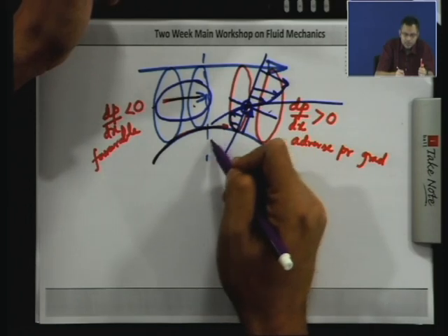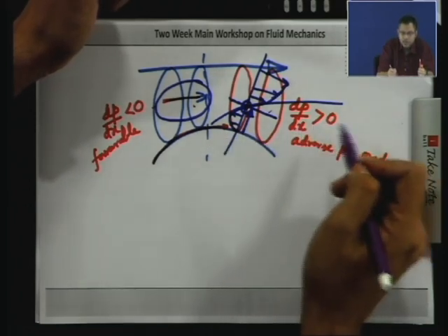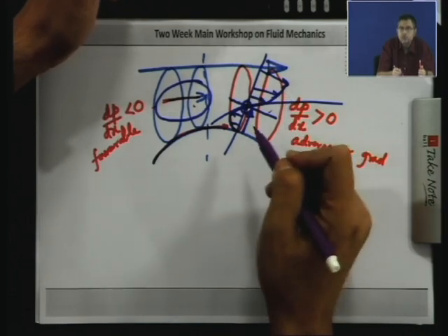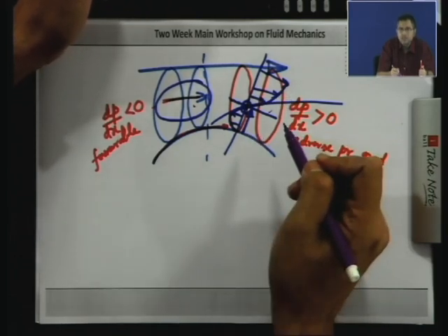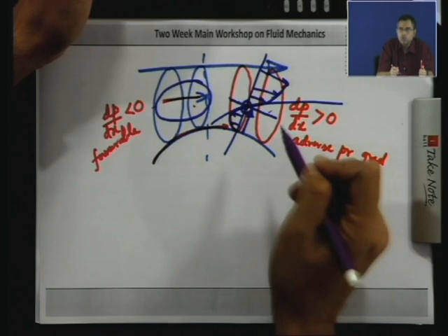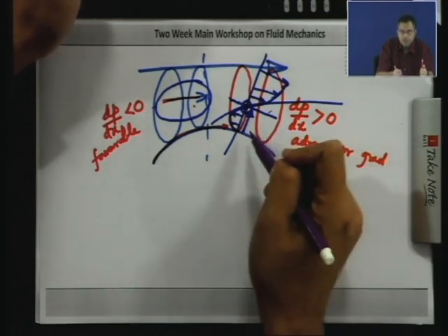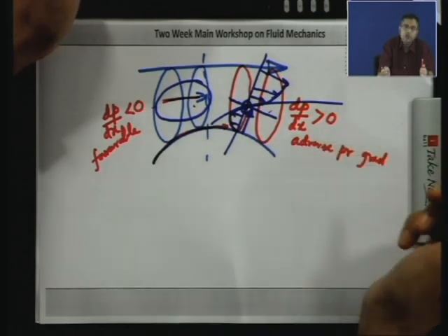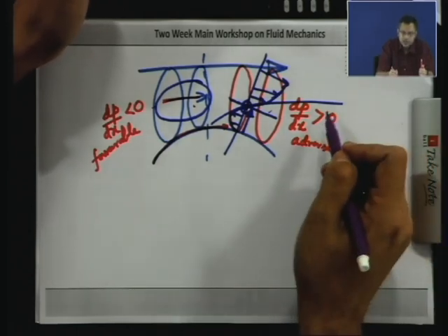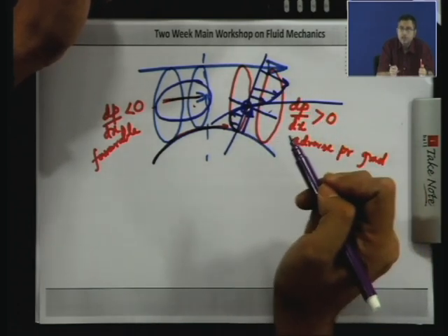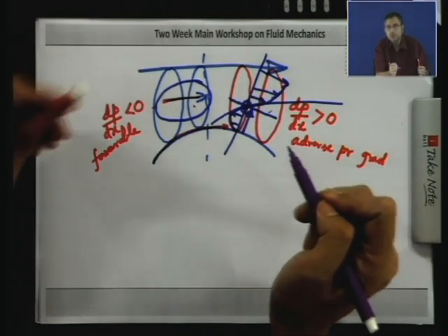But over this region in the adverse pressure gradient, because of slow momentum of the fluid within the boundary layer, because of deceleration that is imposed by the outer stream, the resistance of the wall may make sure that there is a reverse flow, and that leads to boundary layer separation. This is triggered by adverse pressure gradient imposed from outside of the boundary layer.